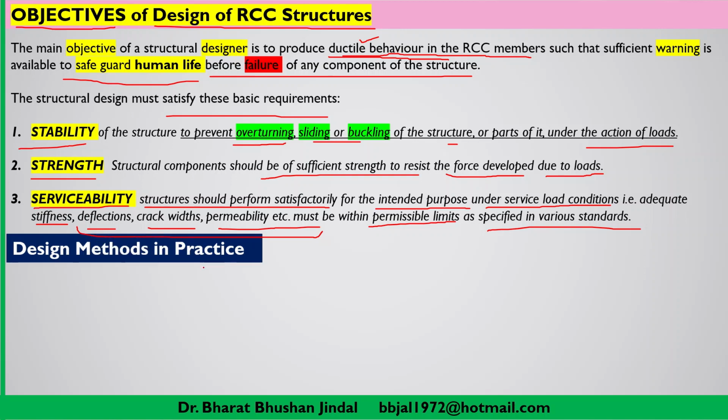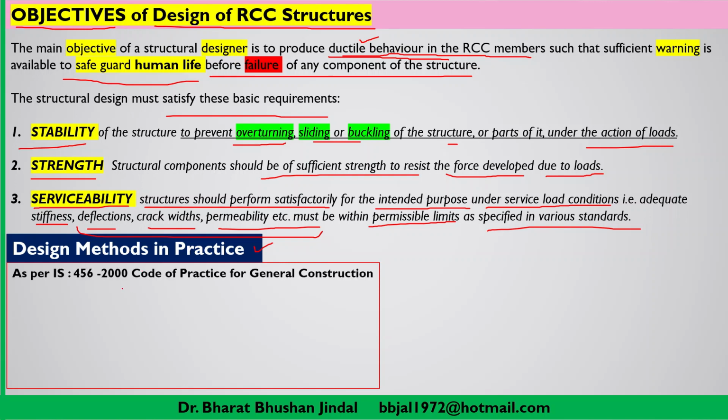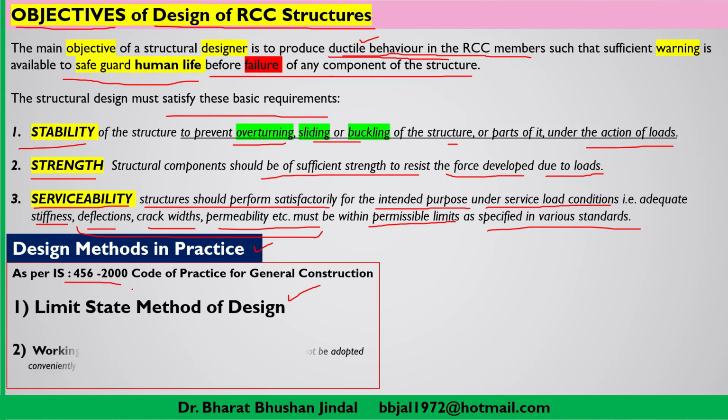Now, what are the design methods which are adopted and are currently in practice? First of all, our guidelines will be available in the code IS 456. So what is the code saying? You can use the limit state design method, that means limit state method of design of RCC structures as per IS 456 recommendations.